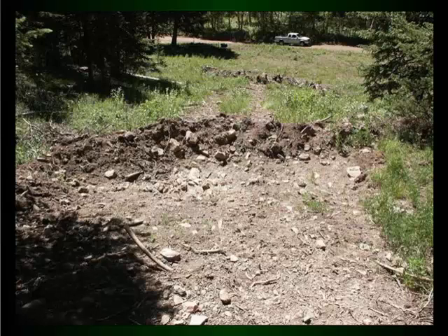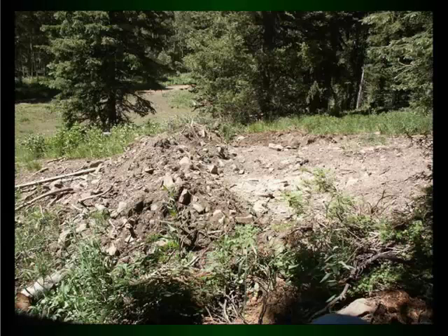The biggest mistake on water bars is people come in and make a knot straight across and basically build little ponds, one above the other. And so instead of taking the water off the trail, they do slow the velocity up, trap a little bit of sediment, but they don't actually get rid of it. So you need to actually make sure you put enough of an angle to kick it off the trail or road. Another example of a water bar with the berm, and once again you can see that it's drained out.